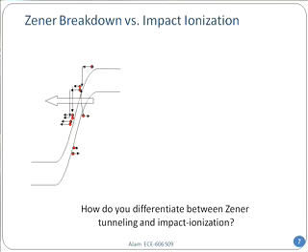But more importantly, the interesting thing is, Zener tunneling is a tunneling process. Electrons slowly go to the other side and it doesn't have too much noise. It's a regular pattern of electrons sort of swimming through the band gap region and getting to the other side. Very calm current, right? Very quiet current.